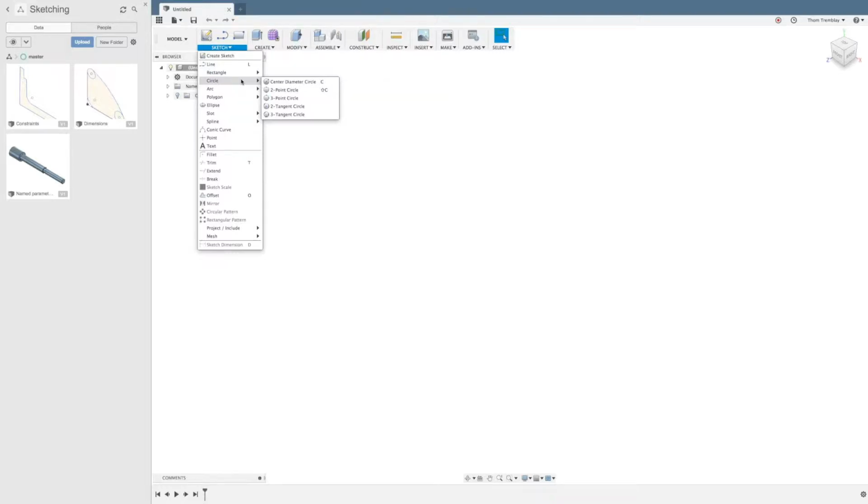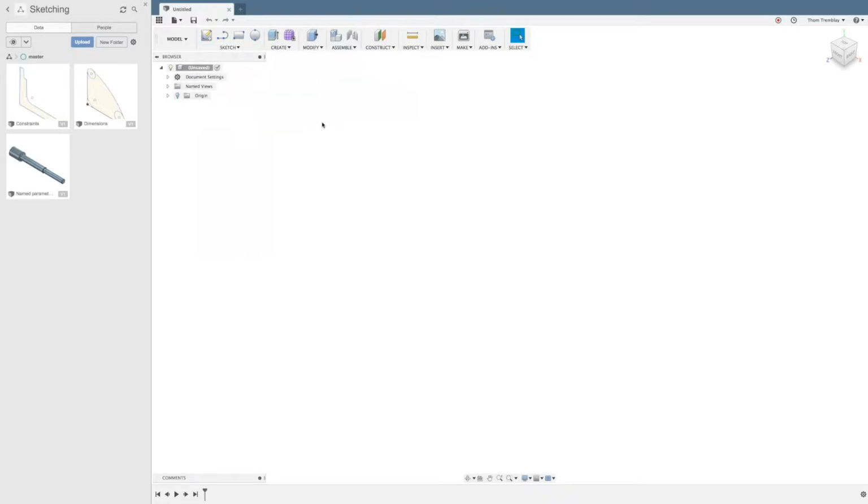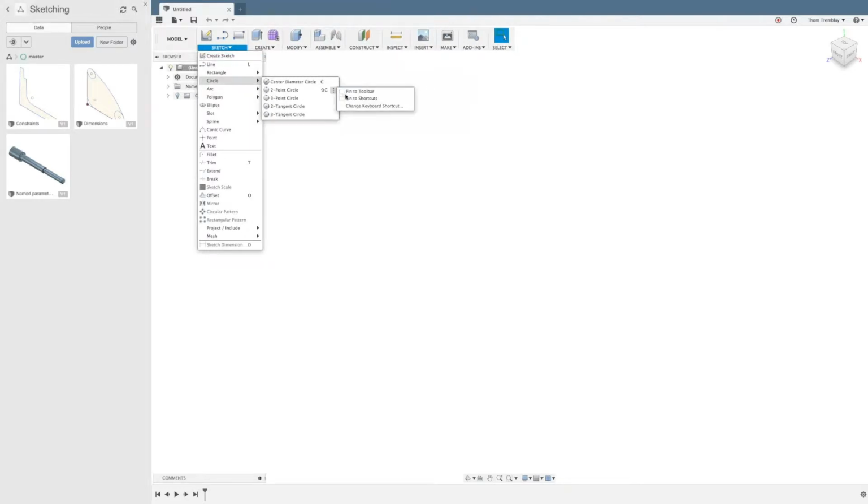Another very helpful way of customizing the interface of Fusion 360, and this is across all workspaces and across any type of tool, is that if there is a tool that's particularly useful to you, you can hover over the More tool again and pin it to the shortcuts, which is the S key menu, or pin it to the toolbar. This will allow you to just quickly access the tool from here. Now, if you ever decide that that customization is not something you want anymore, you can just grab the tool, come back, and deselect it. So just some quick customization.